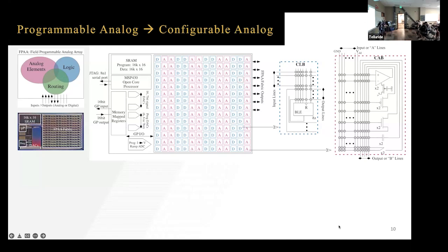But there's a lot of times I want the digital run with my analog. For example, if I'm going to compile certain varieties of analog-to-digital converters, I want some digital with my analog right there. So I'm just going to put it right there. And once you start to go, hey, wait, I don't actually have to have the separation, you begin to realize there's a lot of things you can flow between the two of them. Clearly, in this FPGA part, we're typically not trying to compile a processor because, after all, I also built a hardcore of that in here too.